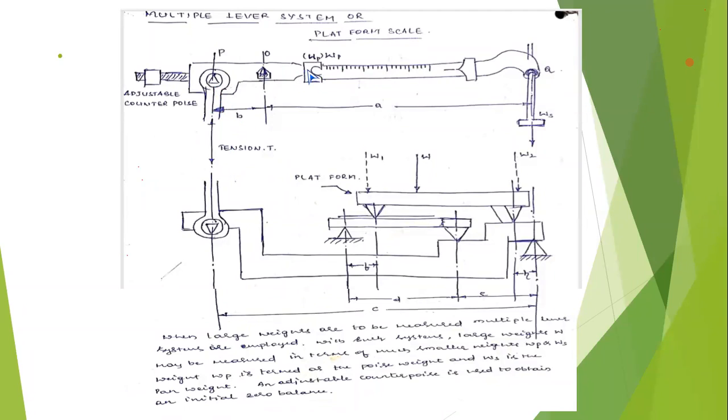The movable poise weight can be moved according to the weight of the bag. So for this example, 43 kgs, place the poise weight of 20 into 2 on the hook provided, and move the movable poise weight near to the third graduation or third line.